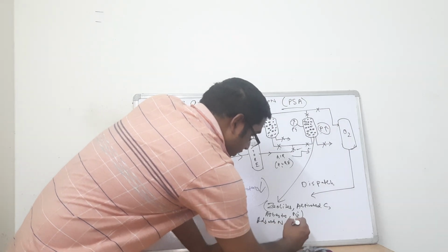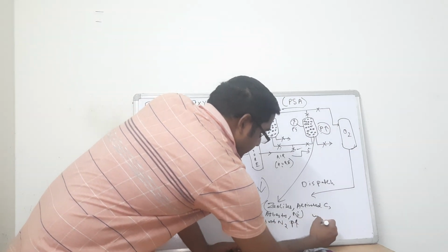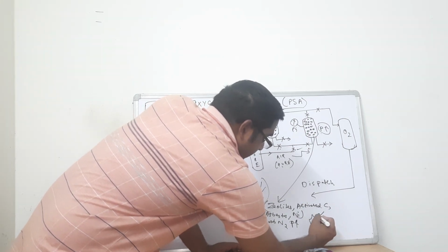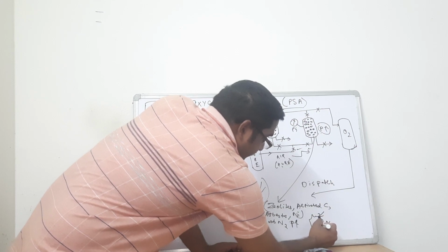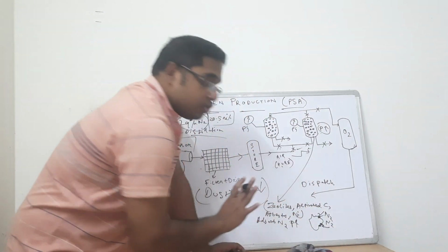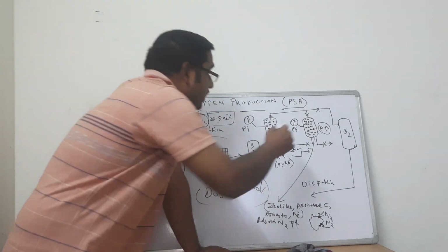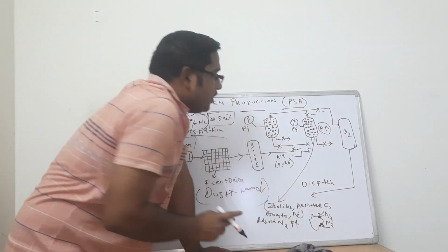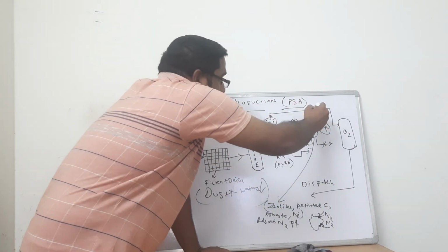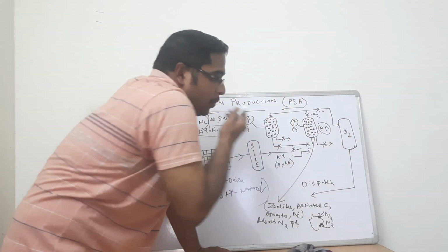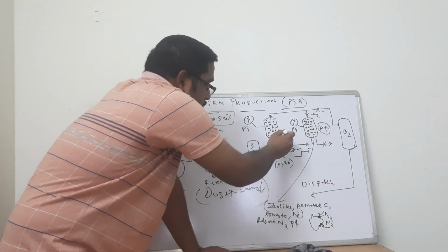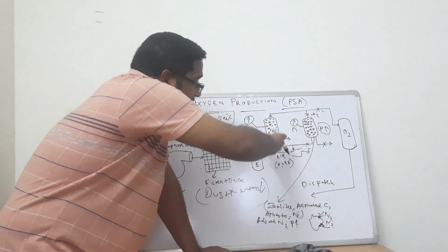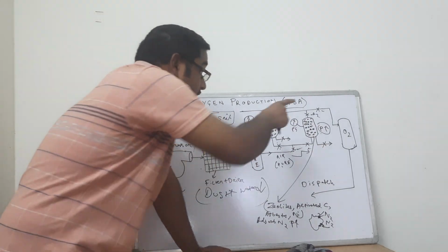They absorb N2 when the pressure is high. So basically this is the structure: N2 attacks the surface pores, the surface areas, and gets absorbed. Once N2 is absorbed, you open this valve. So this valve is open, this valve is open. We see the pure oxygen passes from this valve and gets stored in the O2 vessel. This valve is closed, this valve is closed. So you see that no air is getting passed into the adsorption column that is in parallel to this.